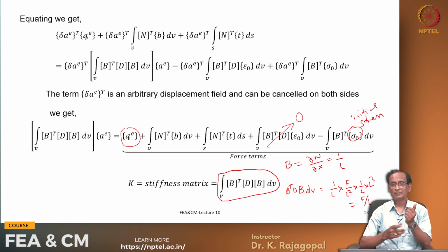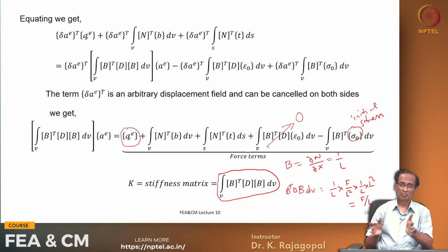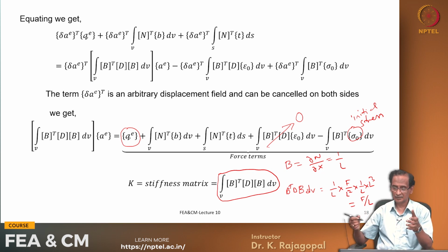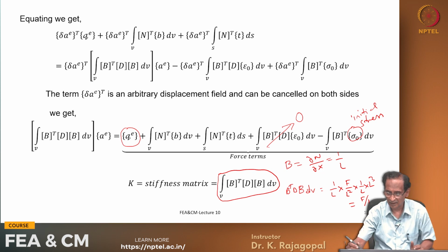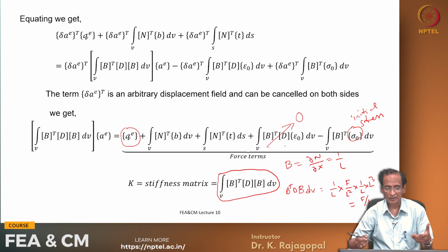We can perform some pressuremeter tests or dilatometer tests, and then determine the in situ pressures. The vertical pressure we normally estimate based on the unit weight, and the lateral pressures we estimate by doing some field tests. So sigma naught is very important, and epsilon naught we normally do not consider.